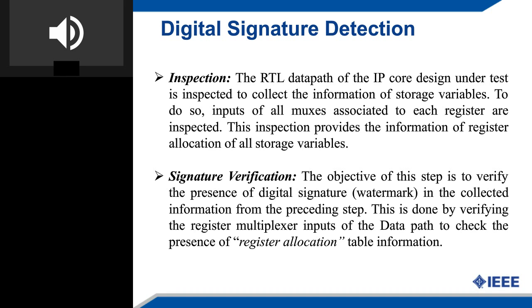Now let me talk a little bit about one of the motivational examples that I have put here to show you how it works. Let's say this is an 8-point DCT code, which is a very important part of the JPEG compression process used in most camera systems. The generic equation is shown inside the green colored box, and the corresponding data flow graph has been extracted and derived. The resource configuration obtained as part of the design space exploration process is 3 multipliers and 1 adder. We will use this information to schedule this graph and then obtain its respective bit stream based on an encoding rule. Let's have a look at how to do that.